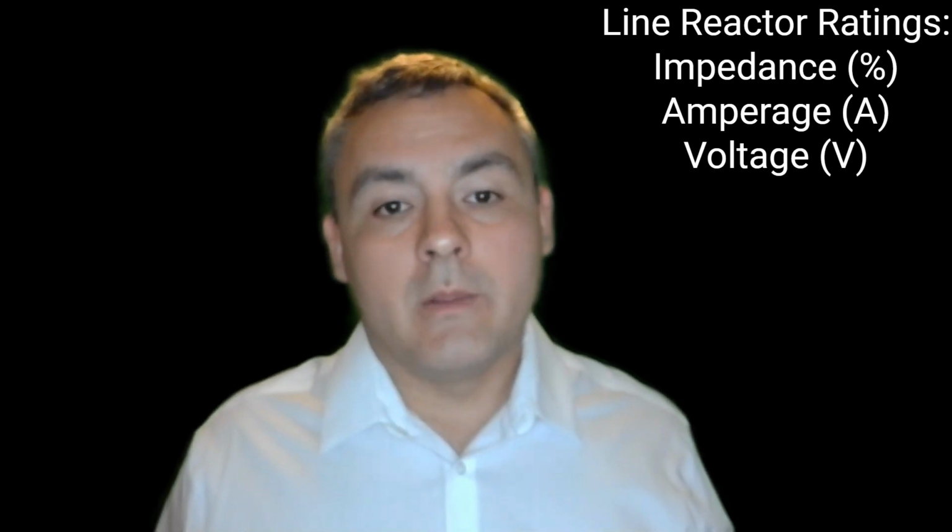Let's start with how line reactors are rated. I'm only going to focus on line reactors for this video, but load reactors are also very similar from a physics perspective. Line reactors are usually rated by their impedance as a percentage value, their amperage rating, and their voltage rating. If they are rated off of horsepower or kVA, then voltage and amperage can be calculated.